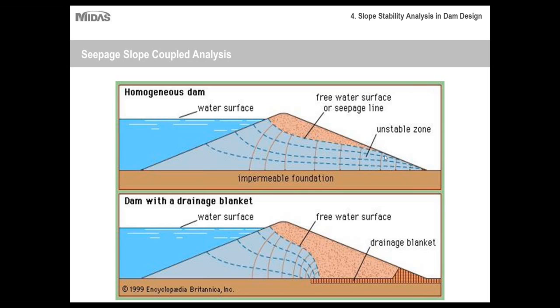So depending on the strength of your materials and the level of seepage, the stability of this side of the dam can be compromised. Whereas if you have implemented a drainage blanket, as shown here, the flow path changes very significantly to the point where all the water is seeping down into the drain and is being safely drained out the other side, while maintaining the structural integrity of this slope here. So that's why sometimes a clay core is used, just to block the seepage or to slow it down, or a drainage blanket or a drainage pipe is included, just to change the direction of the water. So that's one solution that could be created for your dam.